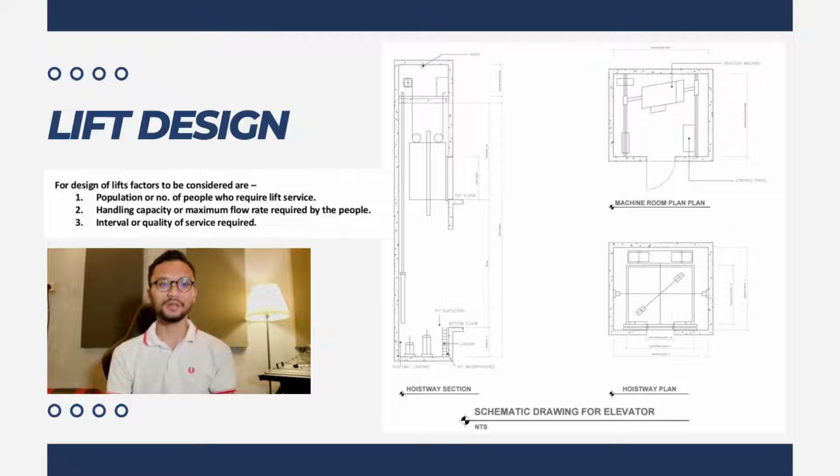The traction hydraulic elevator has overhead traction cables and is driven by hydraulic power, instead of an overhead traction motor. The weight of the car and the passengers, plus the advantage of the roping ratio, reduce the demand on the pump to raise the counterweight, thereby reducing the size of machinery.